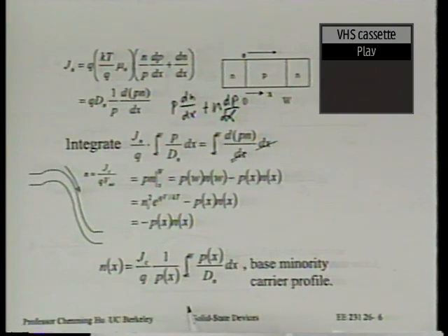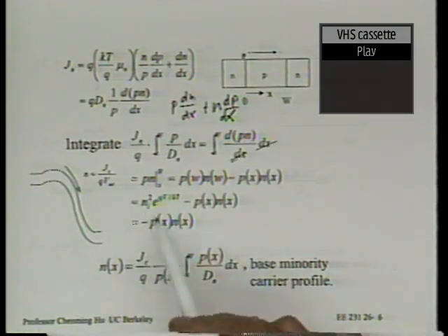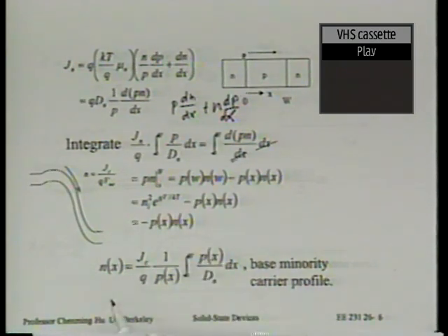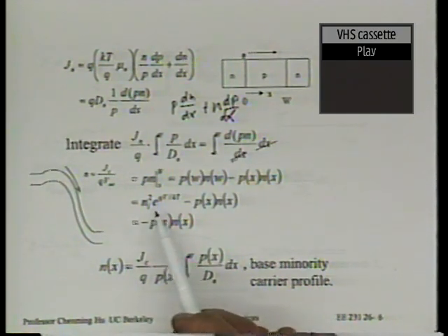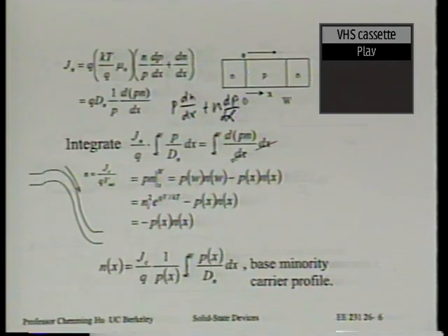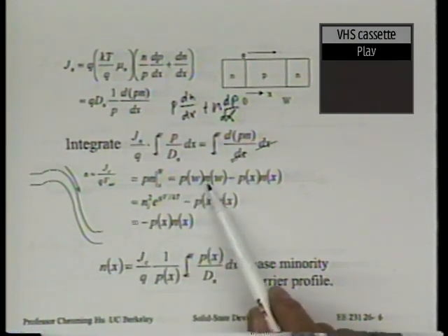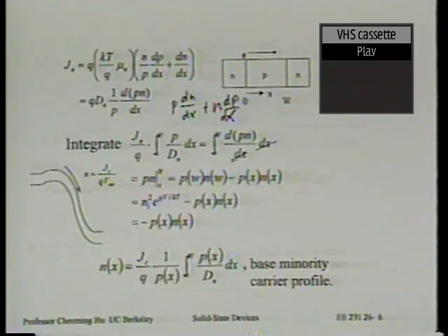At a PN junction, when there's a bias across the PN junction, there's a boundary condition. Some of you may know it as the quasi-equilibrium boundary condition. Others may know it simply as the Shockley boundary condition. At the edge of a PN junction, the pn product is equal to ni squared exponential qV over kT. This is why the minority carrier concentration increases in proportion to exponential qV over kT, because we usually assume the majority carrier concentration is independent of bias. Here we did not even make that assumption. In high-level injection, both can change. But the basic boundary condition is that the pn product is equal to ni squared exponential qV over kT. That's a fundamental boundary condition called the quasi-equilibrium boundary condition.